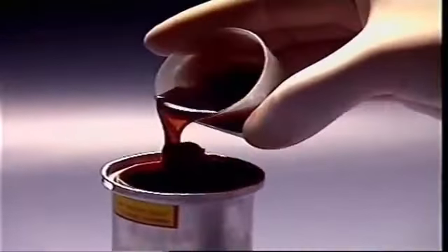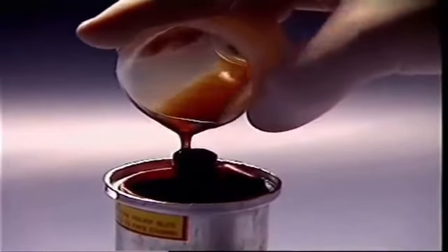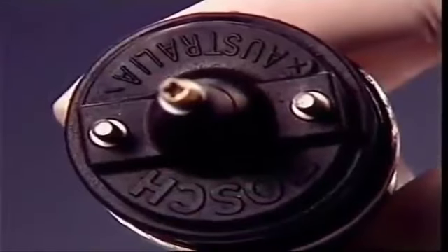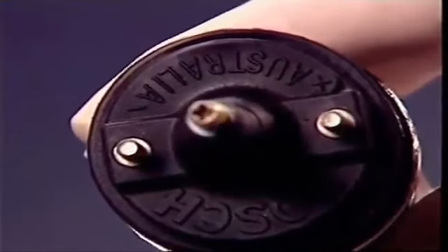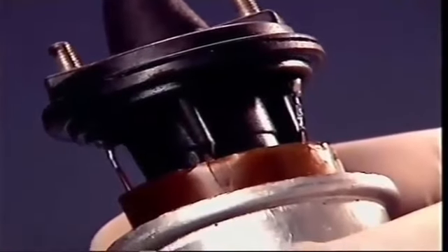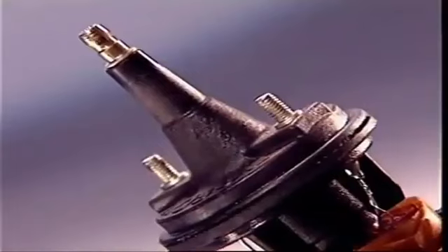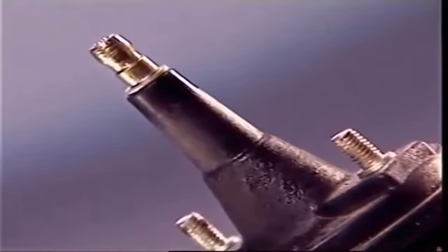The container is then filled with a special transformer oil, which provides good electrical insulation and also permits rapid heat dissipation. The cap has two terminals, positive and negative, for external connection to the primary circuit. The ends of the primary winding are connected internally to each. Provision is also made externally for a heavy insulated center terminal to connect the high-tension coil lead to the distributor cap.